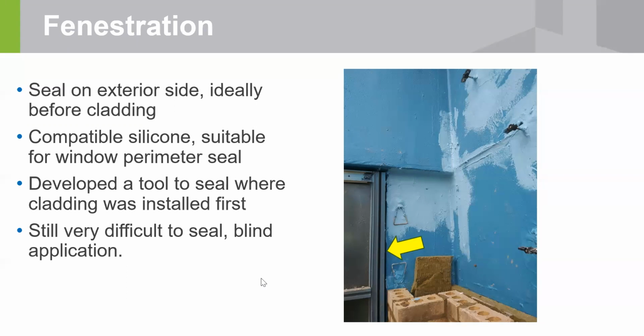Man, I don't like that. What keeps it from getting wet and staying wet? It's supposed to drain, is what they say. They say it's water repellent, which it is to an extent, but it can get saturated. It's like your outdoor patio furniture cushions: as long as the water drains out of it, it'll dry out. But if it traps the water, like at a horizontal relieving angle or a window header, it's going to be wet for a pretty long time there.